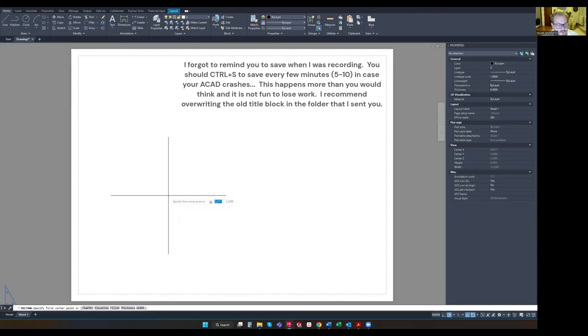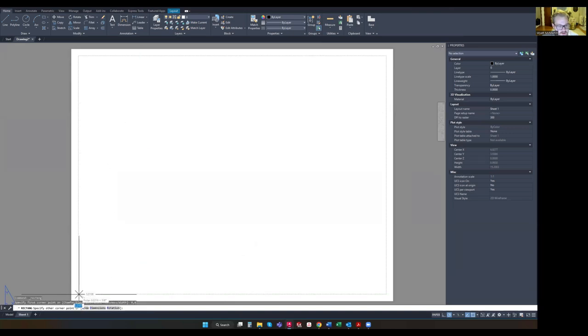and my first point, remember our 0, 0 is already at a 1/4 inch inset on this page, right? So if I type 0, 0, enter, my rectangle is going to start a 1/4 of an inch inset into the page, which is where the print markers are. So I'm going to get my rectangle tool. Remember, you just click up here.